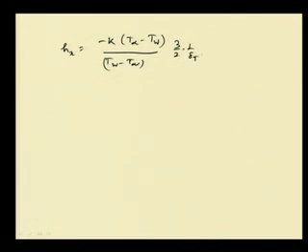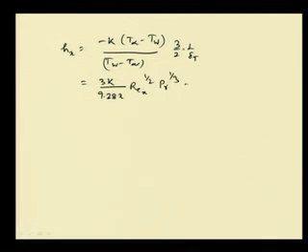So this becomes 3 into k by 9.28 into x, putting all the values, Re x to the power half Prandtl to the power 1/3, and this value is equal to 0.323 k by x Re x to the power half and Prandtl to the power 1/3.